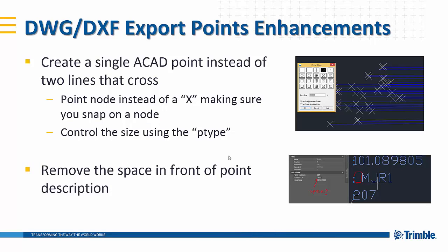Also, we've done some further DWG DXF export improvements. One of the export options is to export points as blocks, where you can choose yes or no. If you don't export points as blocks, you get single AutoCAD point entities, and you can test this by running the PTSTYLE command in AutoCAD and quickly changing the point properties.